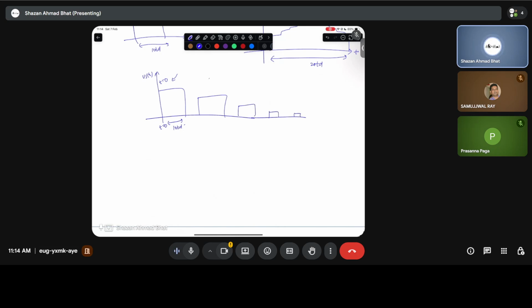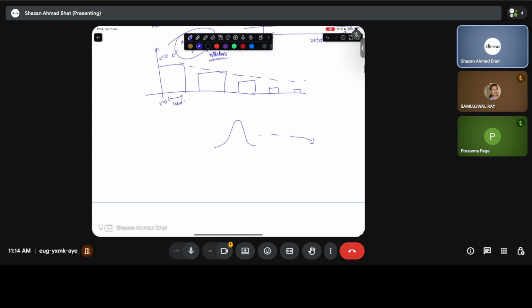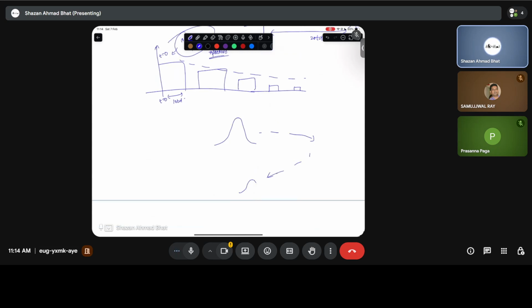I mean, there will be reflections of this pulse, but once the reflections happen, the basic assumption is that the overall thing will finally stabilize. This is not exactly a voltage source, but this is exactly how the reflections of the pulses will diminish in time. And I guess in the first week itself, I showed you that once you give, let's say, even a sine pulse towards the load end, the reflected pulse will be diminished.